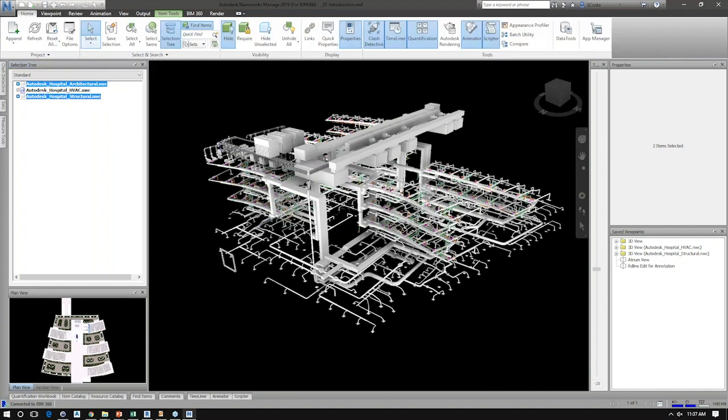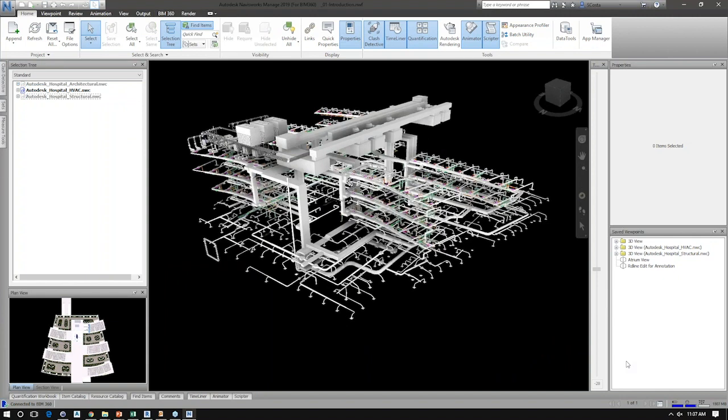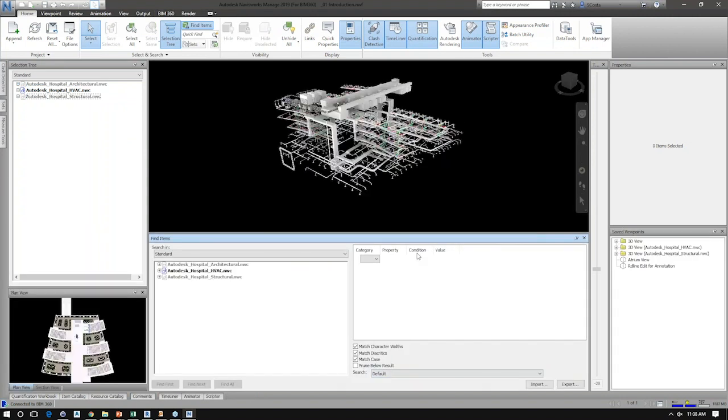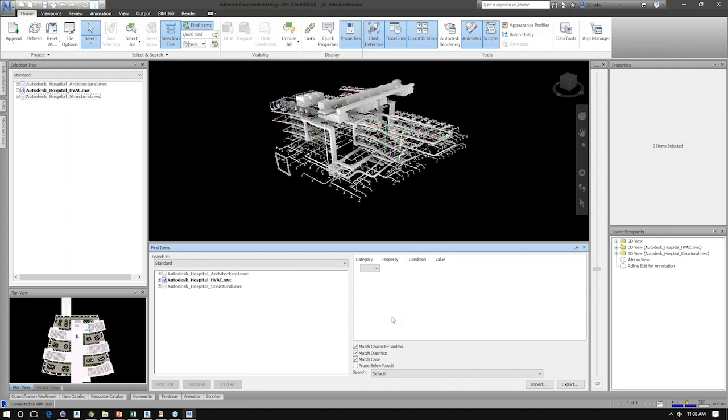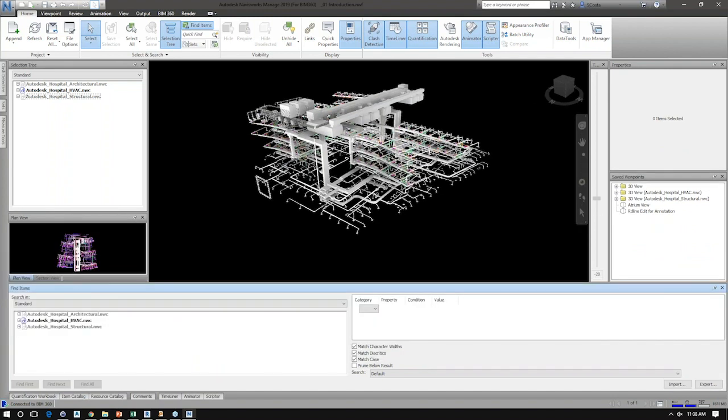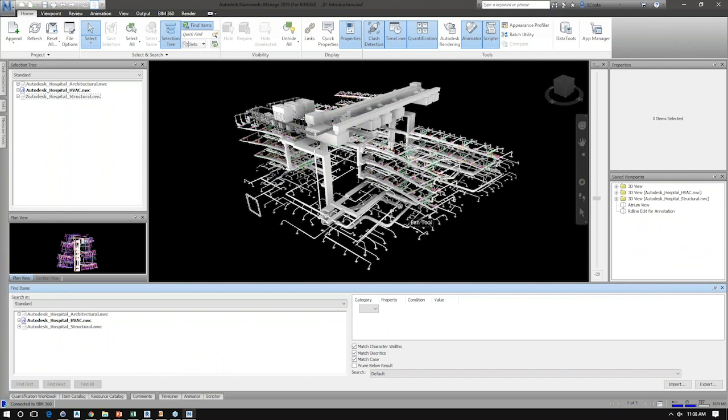And I'm going to talk a little bit about find, which is probably the most critical aspect of learning Navisworks. And the reason I say this is because find ultimately allows you to create things that are known as sets, which allow you to do clash detection and easy quantification of your Navisworks project. Now, in general, the find elements are focused around really building a query, right? It's a logical query that stipulates a certain set of conditions.